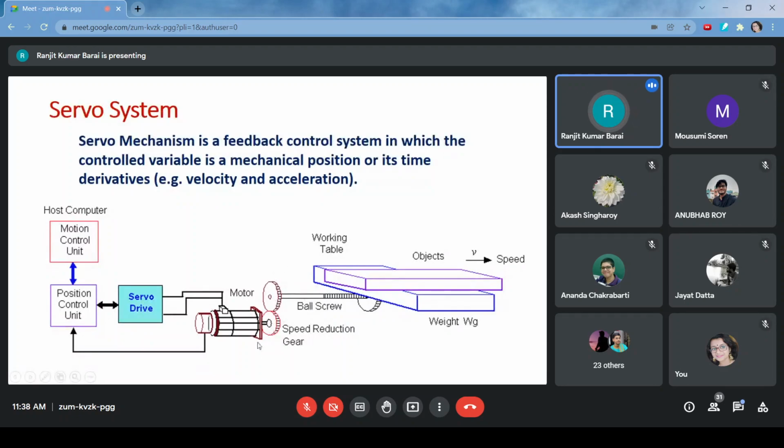Normally the motors run at high speed, low torque, but the mechanical systems require high torque, and they invariably run at low speed. So you need a gearing arrangement. Reduce the speed, so the torque, for constant power, will increase. A very simple schematic diagram is shown regarding this mechanism.